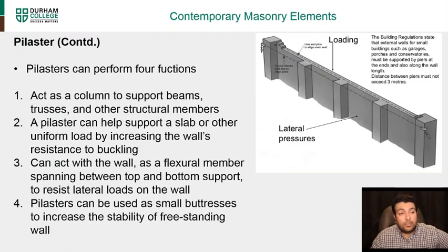Actually, the pilasters can perform four functions. They act as a column to support beams, trusses, and other structural members. A pilaster can help support a slab or other uniform load by increasing the wall's resistance to buckling. And they can act with the wall as a flexural member spanning between the top and bottom support to resist lateral loads on the wall.